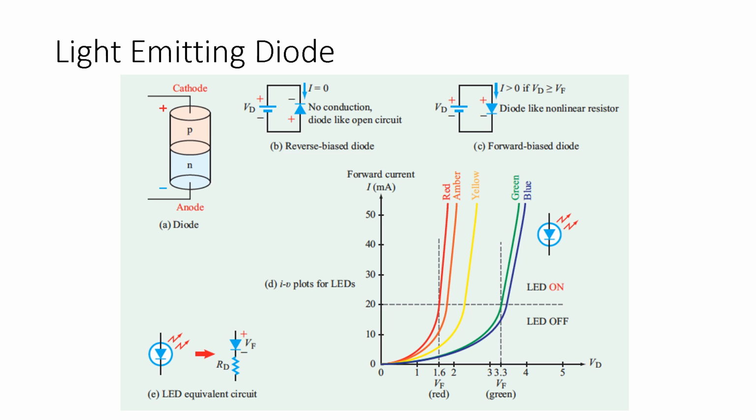In actual practice, these are nonlinear relationships, and because of that, you are going to see some slight dimming if you're a little bit underneath the forward voltage for that LED. So let's say again, you need 2 volts to make the LED turn on, and you give it 1.7. Mathematically, that says the LED isn't going to turn on. In real practical engineering, 1.7 is going to make that LED turn on. It's just not going to be as bright as it could be with 2 volts.